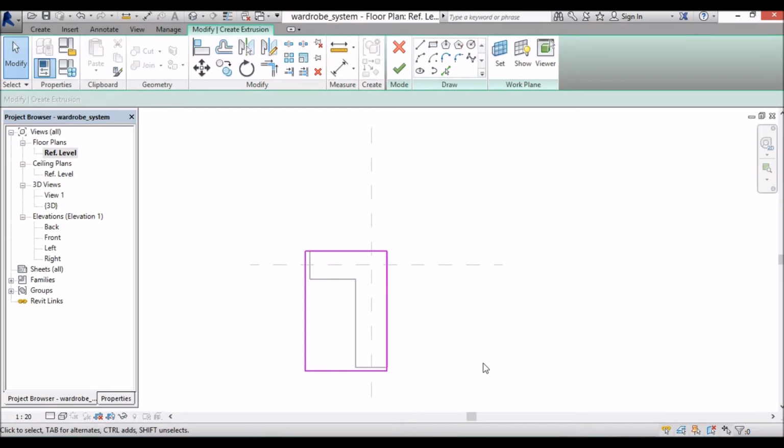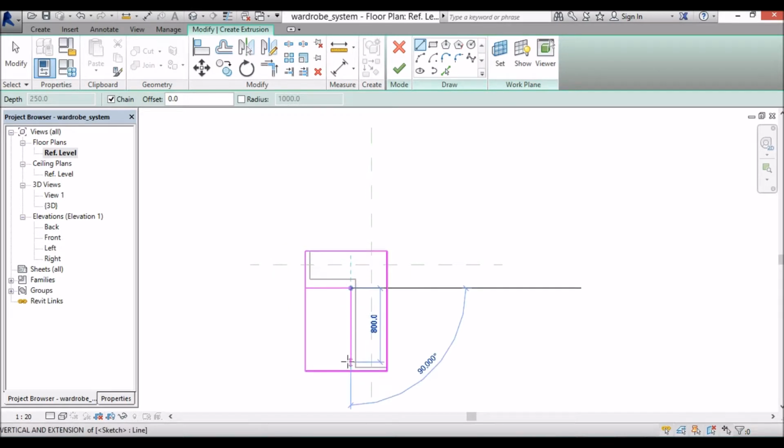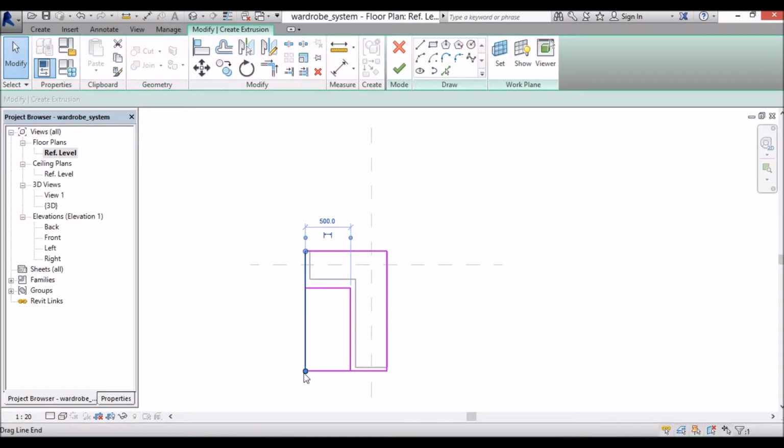There we go. Now to make the L shape, I can select the line tool and then I just draw my lines where I want them to be to create that L. Okay, escape again on the keyboard. Now I can easily modify this rectangle just by clicking on this line here, and see this little circle here. You can hold down your left mouse key, and drag it upwards, and there we go. And do the same with this one here. And there we go, we've modified a rectangle to be that L shape that we wanted.